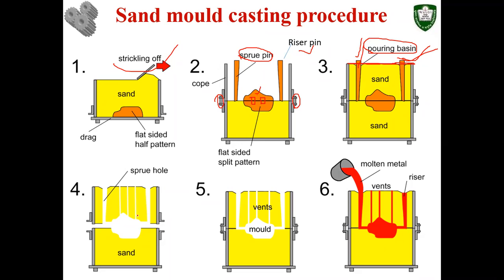Okay, again, from the drag, you take off the first half of the pattern. Then from the cope side, you take the pattern out. You take the whole pattern out actually. Okay, and then you put them together again.